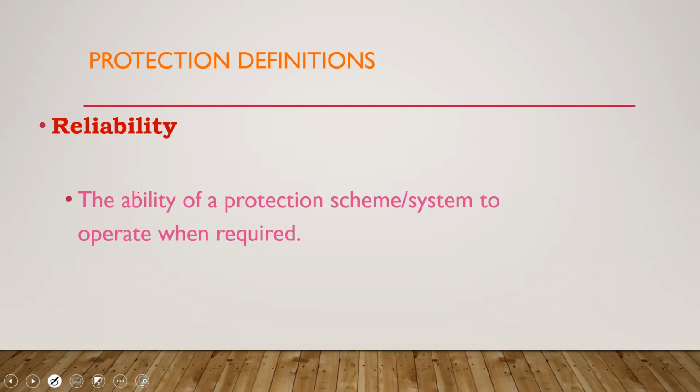You have a number of ways. And I come back to something simple, which is in your home. Let us say a breaker went bad and you need to go and buy one, but the people at home still need power from that circuit. You have a couple options. You can either take that line and put it directly on the bus bar, or you can put it on another breaker. Obviously, it will not be a permanent solution, but you are replacing the breaker, and the people still have power.